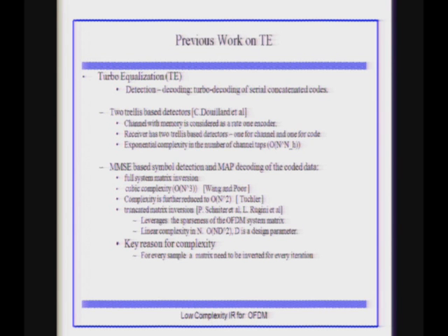they considered the channel as a rate 1 encoder. So you have the channel as a rate 1 encoder, and you have the decoder. That's another encoder and decoder. So you have two decoders, one on the channel and one on the trellis decoder, whichever, BCJR or whatever. These two work together as a serial concatenated scheme, and it has exponential complexity, and that was the original idea proposed.